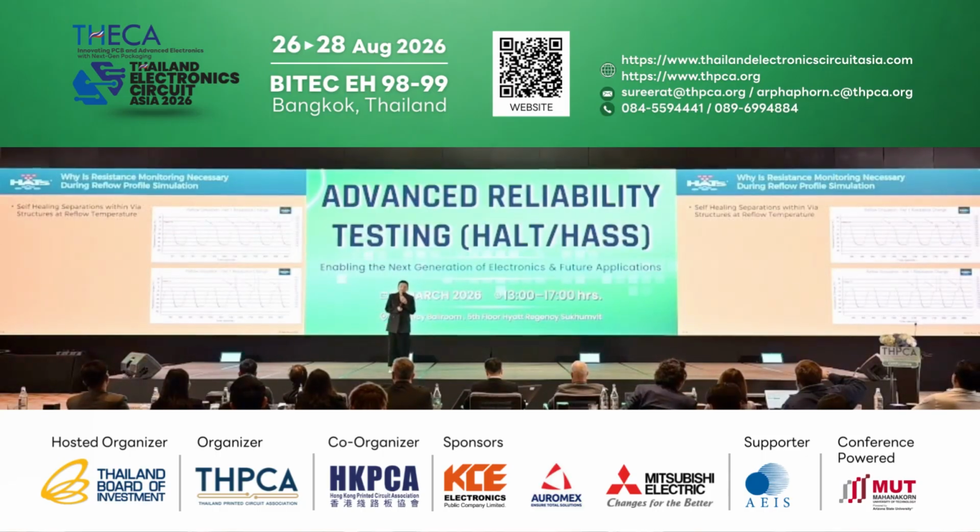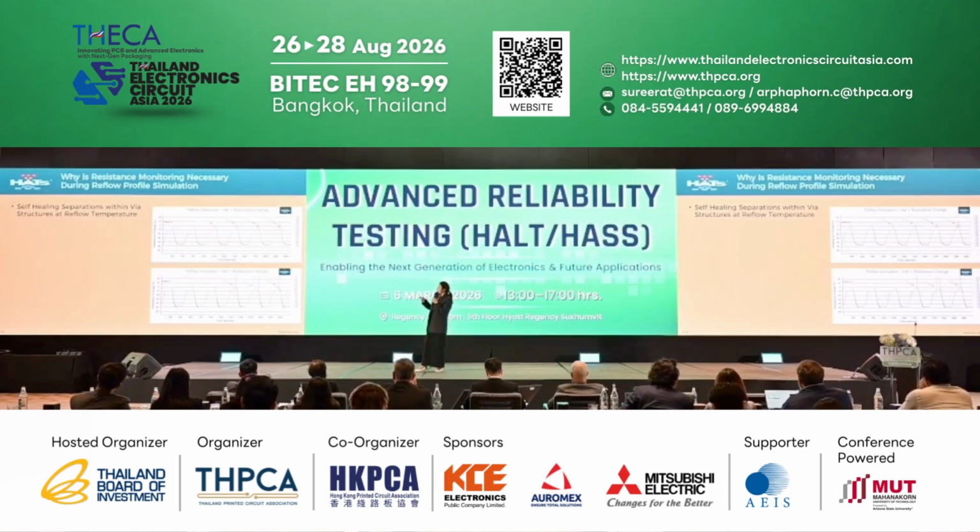But some failures can happen already in the later reflow cycles. For example, this is a test we've done to six cycles, and we monitor the resistance change.